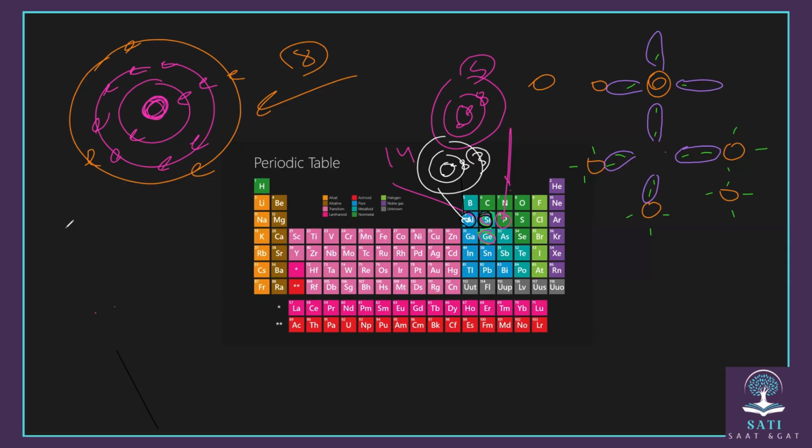So that means on the valence level it has 3 electrons. If we put aluminum here, we'll have 3 electrons. One will be here, one here, and one here. What about the third bond? It will have a gap. It will be empty. So no electron there. So when we add aluminum to silicon, we'll have gaps. That means we have fewer electrons than needed.